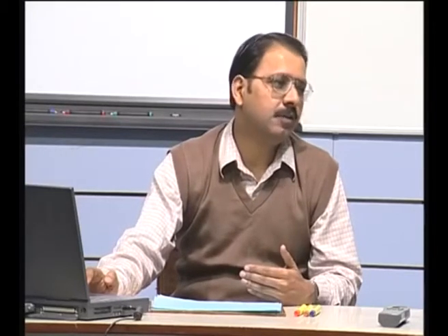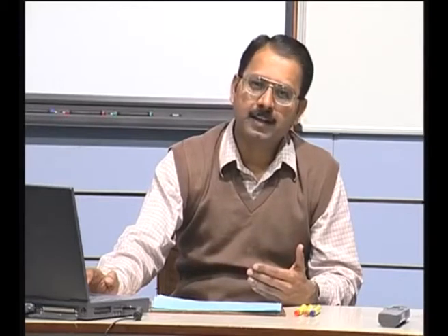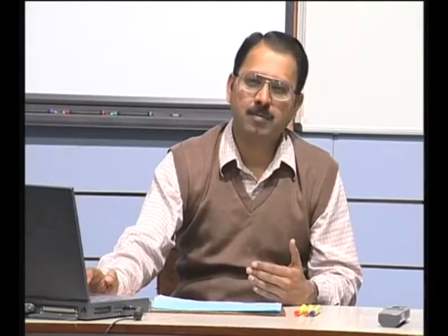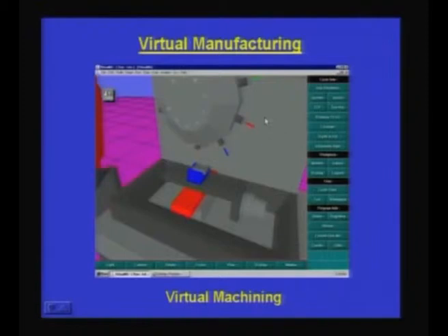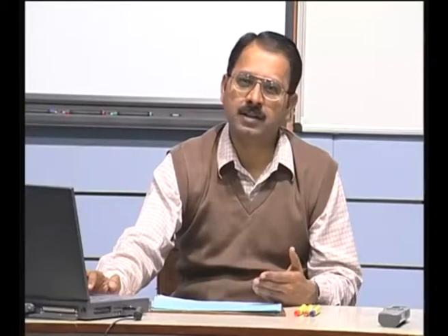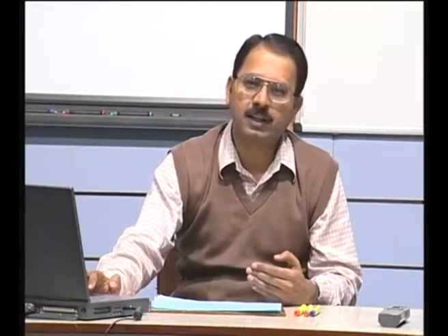Now, that means you have not taken care of the collisions which are likely to happen when you are planning this. If I can exactly simulate the same machining scenario in front of my computer, where I can build a model of a machine tool, input my program written to cut the part, give the raw material geometry and carry out a machining simulation, then if any collisions are likely to happen, you can visualize this, or the computer can tell you that here are the problems which are likely to happen.